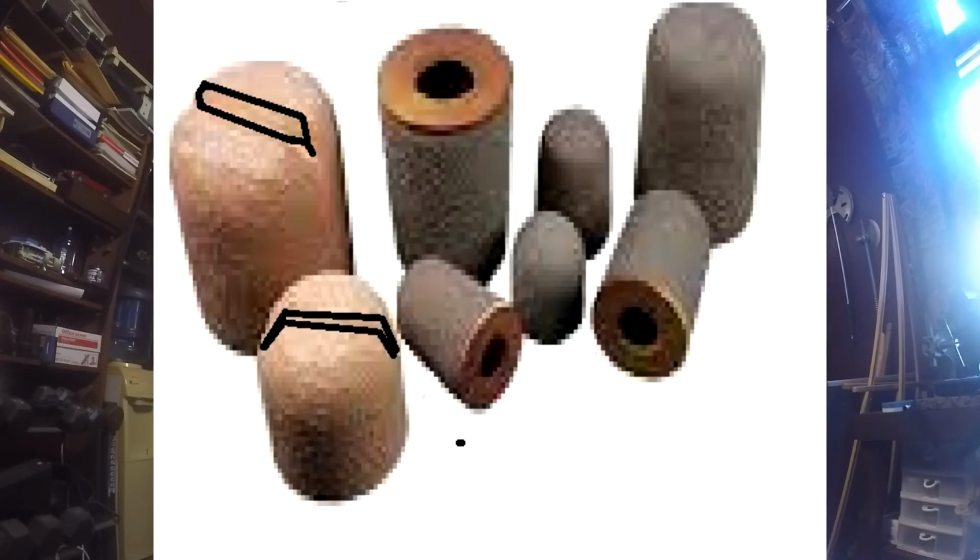Now, this next one is kind of a specialized one. The one after it that I'm going to show you is an example of a blind riser. Now, the rightmost one, you make a blind riser by making that basic form right there, where the bottom is a little bit bigger than the top, so that you can pull it out of the sand easily.